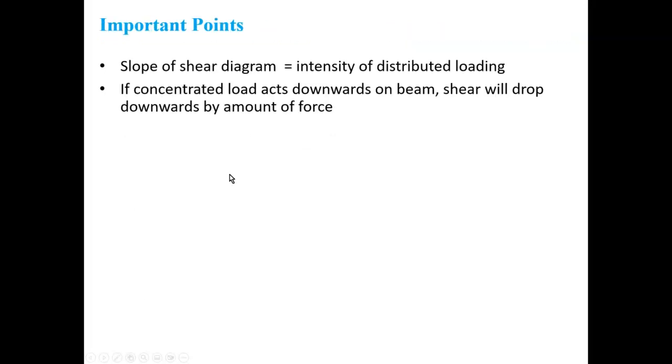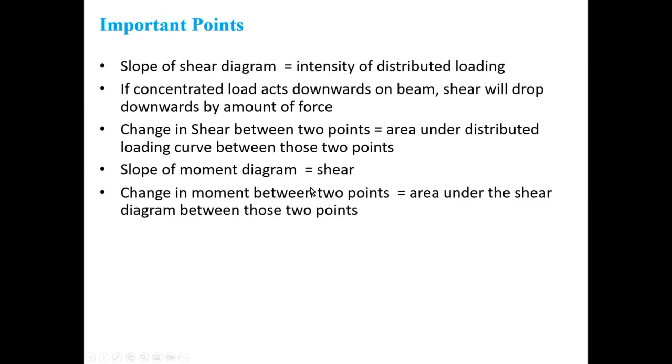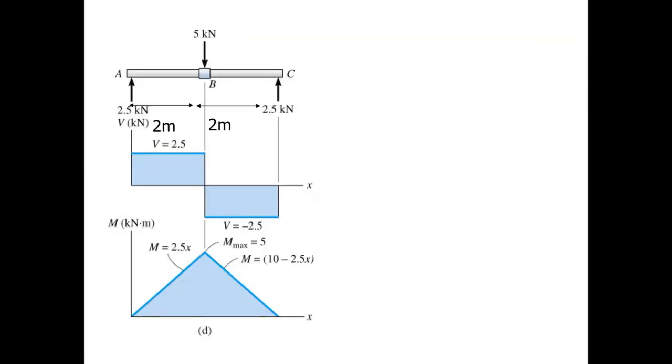All right. So these are the important points. When you want to plot shear force and bending moment, the first step is to find the reactions. The second step is to find out how many zones there are. The third step is to find an expression for W of x, the distributed load. And from the distributed load, you start integrating zone by zone to find V of x, and then integrating V of x to find M of x. So let's practice this in some example cases.